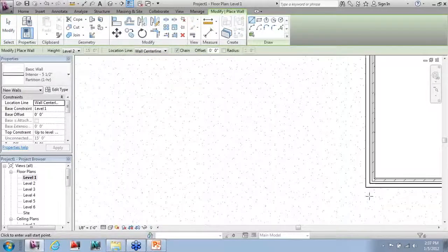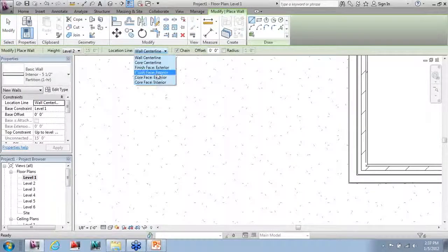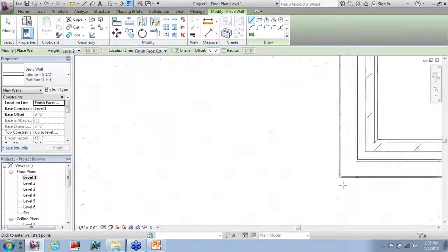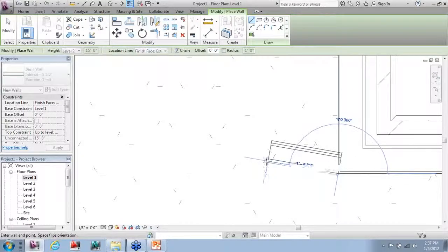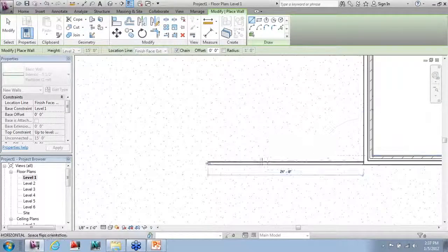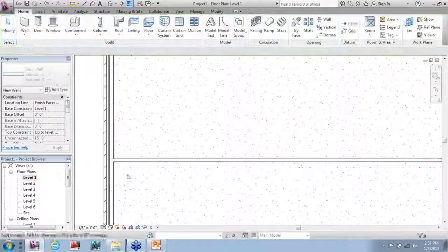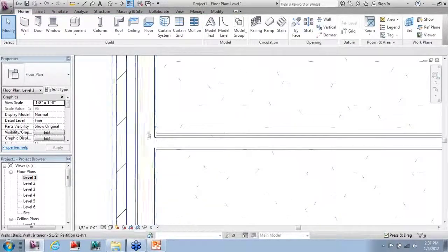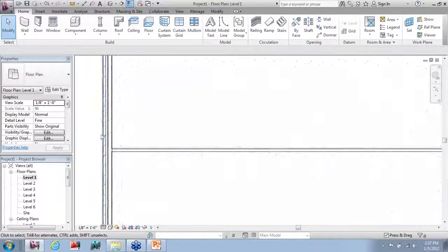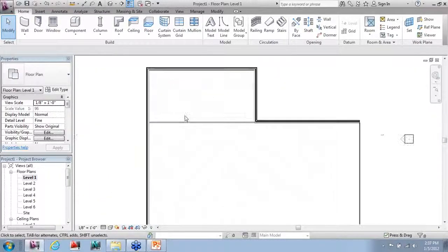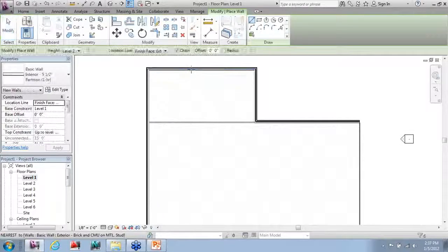Again, I'm going to use the Wall tool. And what I'm going to do is go ahead and start drawing some walls into my structure. Now you'll notice as I draw these walls, they start to automatically clean up with one another. So regardless of where I place them, you'll notice that there's cleanups occurring. This is a really great tool and feature inside the Revit program that we're able to create these quick cleanups.